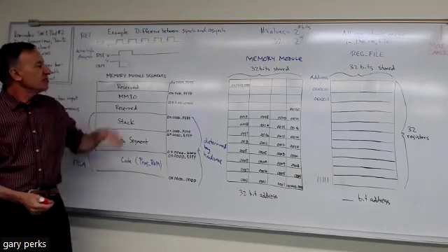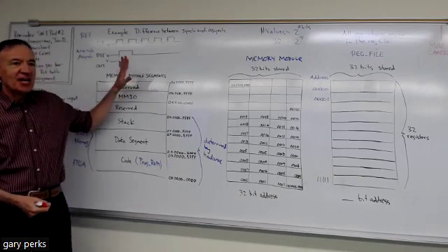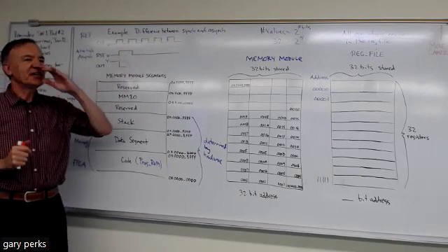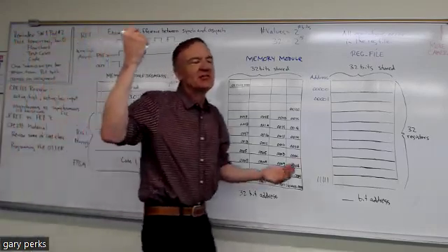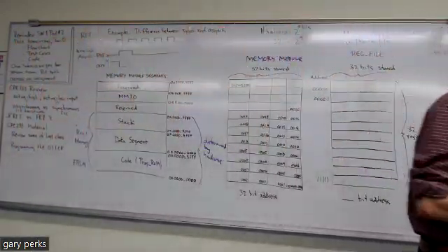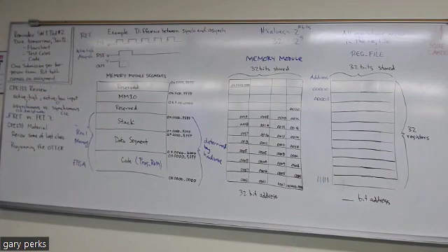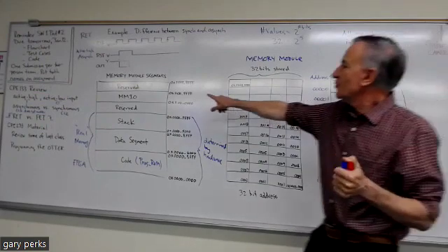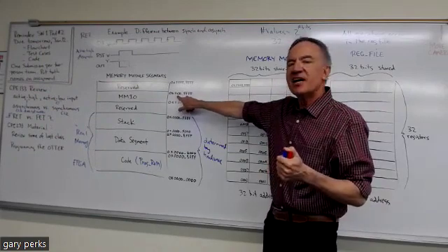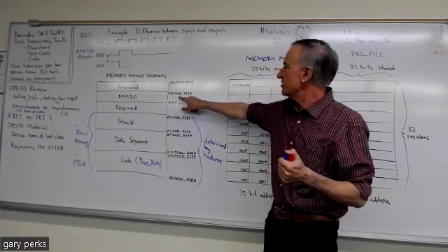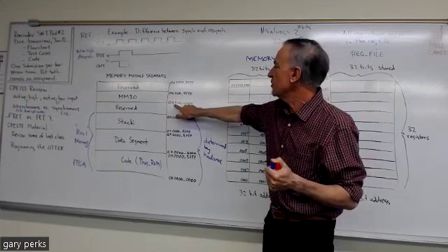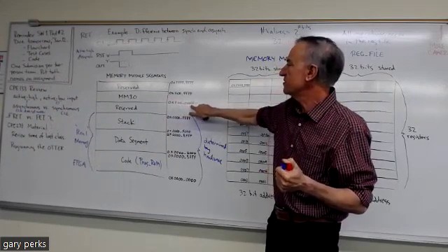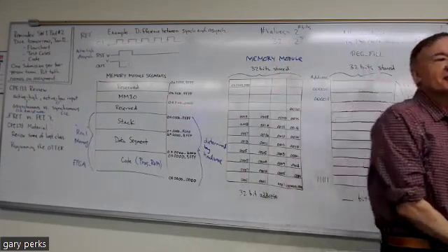And then also MMIO, memory mapped IO. By the way, we talked about this last time. What's memory mapped IO? What does it mean? Where did this address come up last class in the assignment? This one here, 11000000. Yeah, that was the switch address.